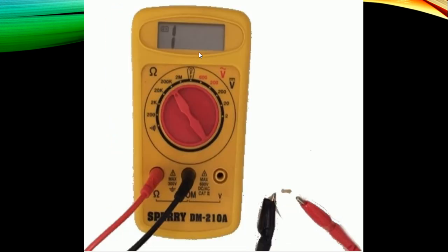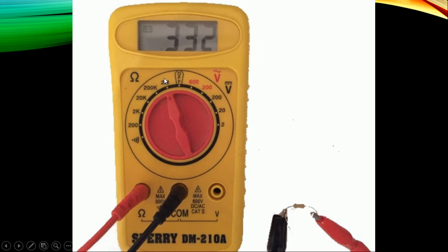Okay, next image. Actually, this is the same resistor that was measured in the previous image. But why does the multimeter display a value of 1 when there's no change in configuration in the probe ports? It is because you put the selection knob in 200 kilo ohm. With 200 kilo ohm, since you are measuring a 330 kilo ohm, a value higher than the limit, it will just display 1. So if you want to correctly display the value of the resistor again, you have to return it to 2 meg so that it could read, because with 200K, the 330 kilo ohm is above its limit. So it will just output 1 in the display.